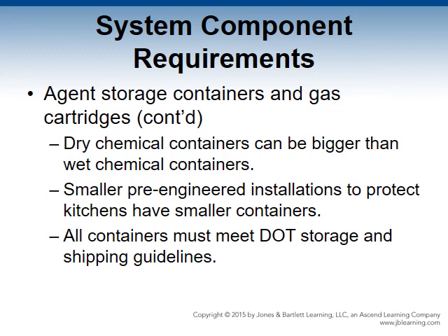Container sizes. Dry chemical containers can be bigger than wet chemical containers, depending on the hazard. Containers can hold hundreds or thousands of pounds of a dry chemical agent. Larger, energized hazards may require separate containers for the agent and gas. The containers must also be as close as possible and practical to the hazard.